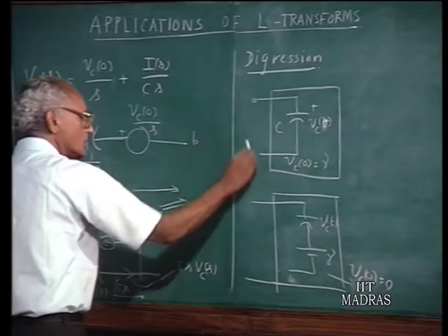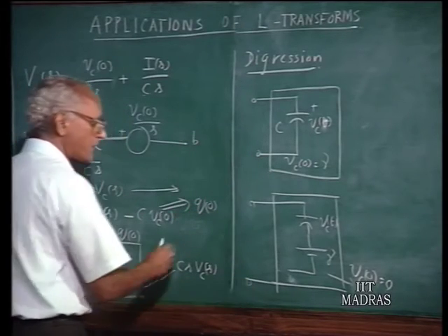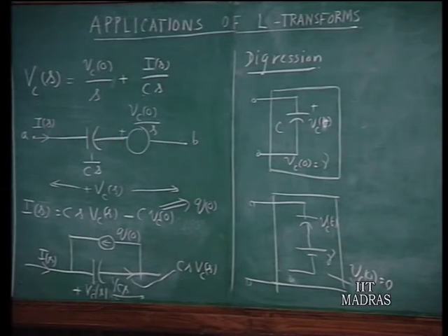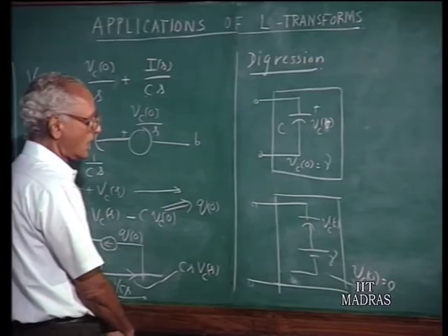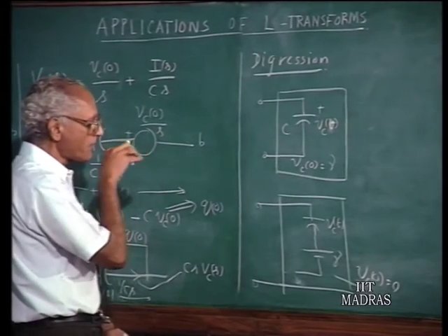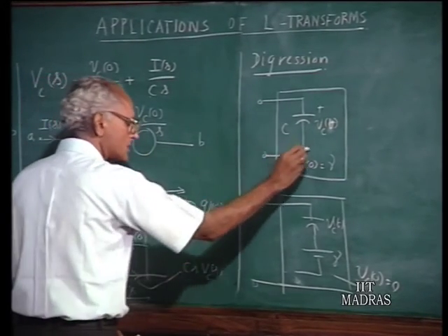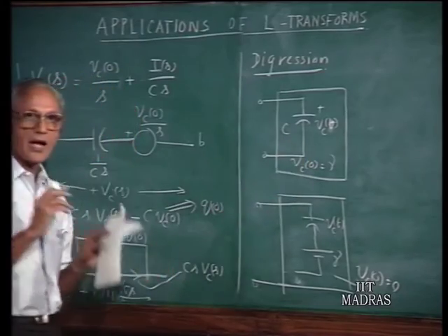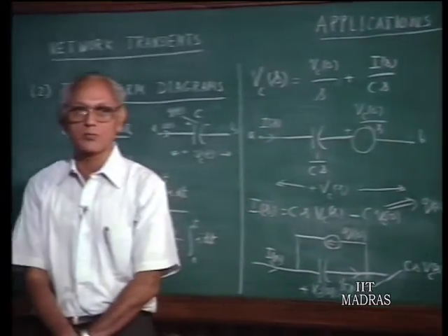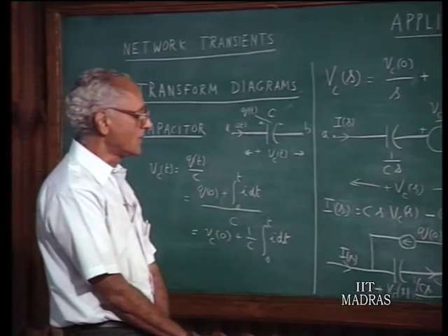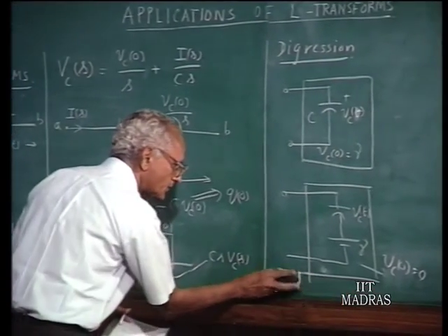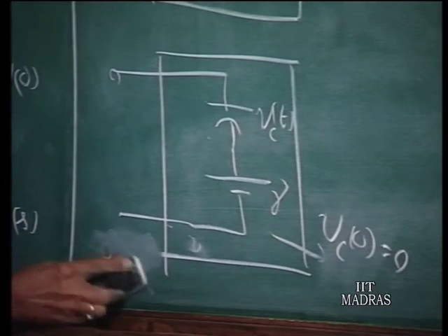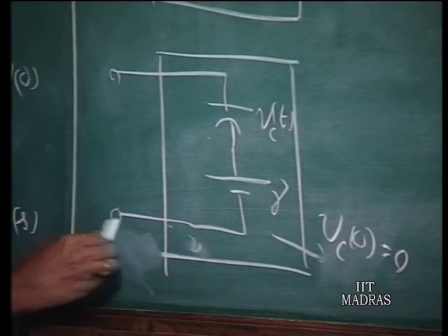So if these two capacitor systems are given to you in two black boxes, they provide identical terminal relationships to whatever circuit they are connected to. In other words, from any external measurements, you will not be able to distinguish between these two. They have identical terminal relations for all possible experimental situations. In other words, these two are equivalent for every conceivable excitation.